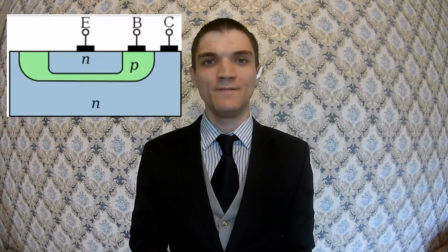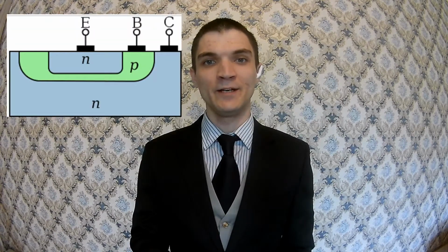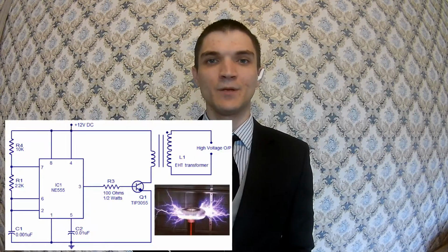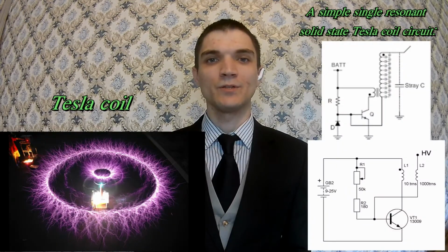Then the question remains how to remove excess charges from the top point of the conductor. To do this, you need a device that would help the conduction electrons leave the conductor: the electron emitter. The emitter can be based on a low-power, high-voltage generator capable of creating a corona discharge around the emitting electrode at the top of the conductor.